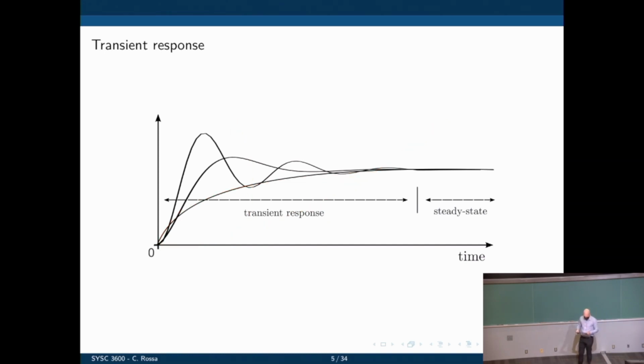So the idea now is to look at these systems. We know how the damping ratio can create this type of response, but the idea now is to quantify these signals. What can we say here? There are two different responses, the transient and the steady state. The question now is, where does the transient end? Where does steady state begin? This is something we could measure. We can call this the settling time, which is a function of omega n or a function of zeta. And this settling time is something we'll be able to control by changing the damping ratio of the system.